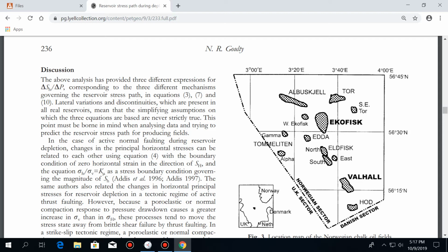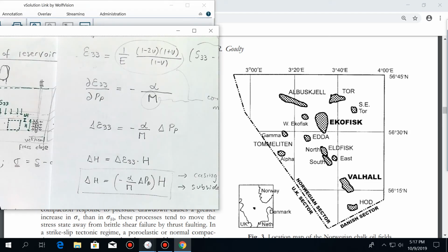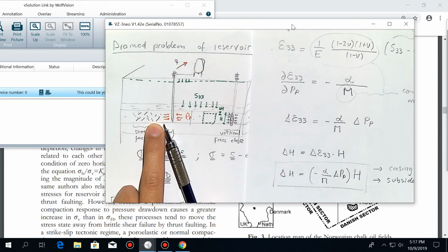Then they figured that in order to avoid subsidence and continue producing oil, you would have to maintain reservoir pressure and not lower it too much, because otherwise the surface will just sink. And particularly for the case of Long Beach, those reservoirs are relatively shallow. That's another thing that helps subsidence to propagate to the surface.